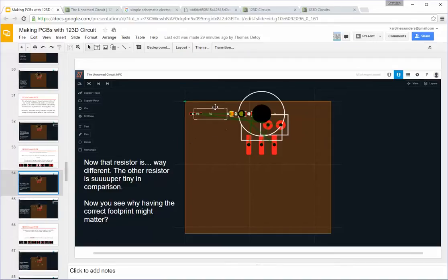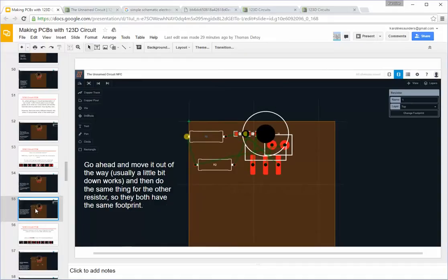So notice how much bigger we made the resistors. That's literally what the resistor size would be in relation to the board when we're soldering. If we have the wrong size, it's going to be difficult to solder and we're going to have a bad time. That's why we're making the resistors bigger. So make sure that you've made both of them this new kind of resistor.